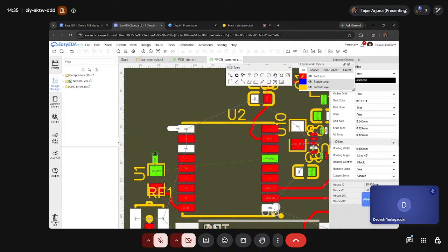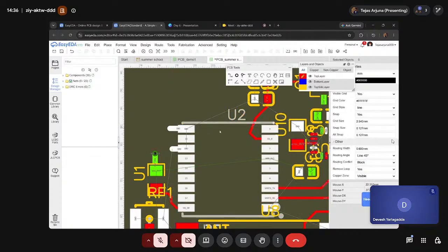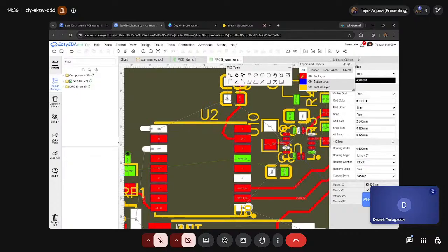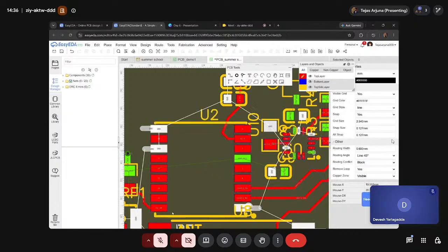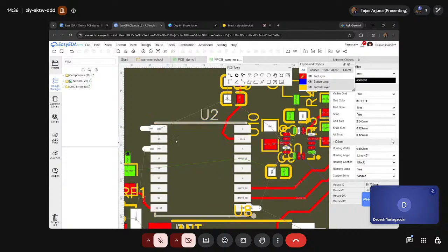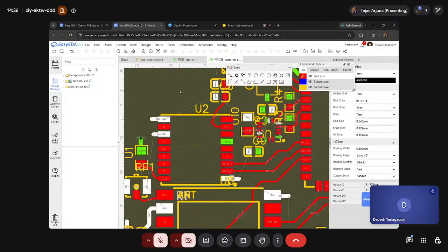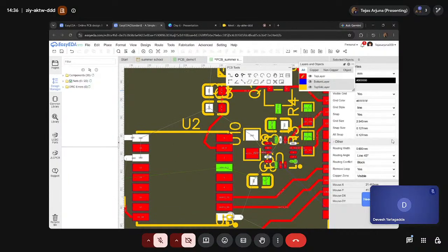See, in these types of devices, there will be multiple grounds. Why are they present? Sometimes the devices, even if they have multiple grounds, won't be shorted among themselves, and in some devices, they'll be shorted. If they are shorted, these grounds are used for getting more current when the process is getting hectic. But if they are not shorted, then these grounds are for different purposes. This may be a digital ground, this may be an analog ground, this may be a power ground. So there will be different purposes we assign the grounds for. That is the reason we sometimes have multiple grounds, multiple VCCs and all.